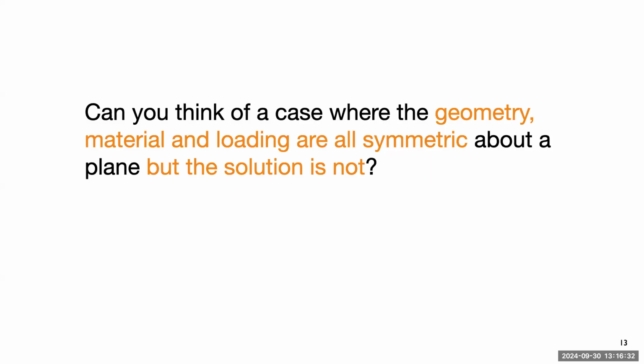Okay, so I'll show you some examples. If you flow over a symmetric object, like a sphere or cylinder, then if the flow is going slowly, you'll get symmetric flow afterwards. But once the Reynolds number is higher, or the flow is faster, it's not stable to get a symmetric solution. You get a solution that isn't symmetric. You get vortices being thrown off. And that's just the maths, even if it's not due to experimental error in your geometry or anything like that.